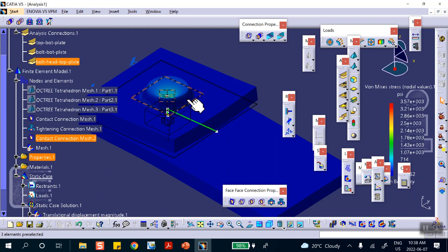When you tighten it numerically, it actually goes sideways to the hole and it penetrates it. So in reality, you have to create a contact between the shank and the top hole, the shank and the bottom hole, and say, don't penetrate. Right now, I don't know, because these are almost zero clearance there. As soon as it deforms, it goes sideways, one way or other. It penetrates it. So the level of these things, modeling will tell you how reliable these things are going to be.